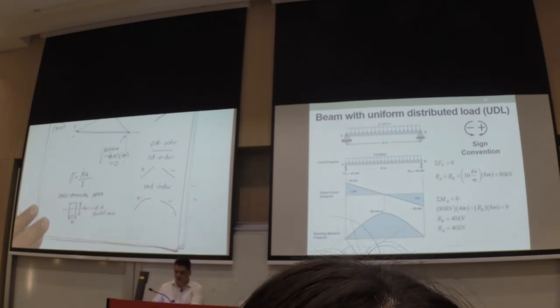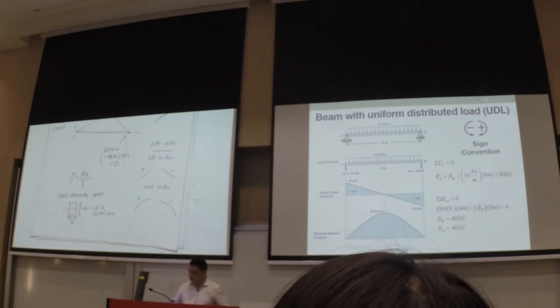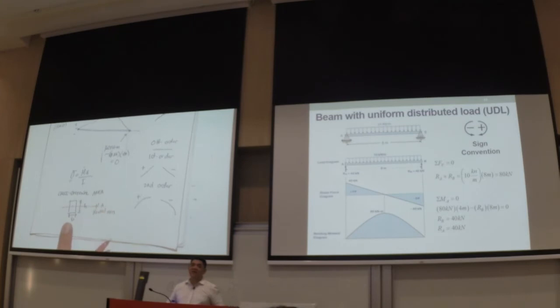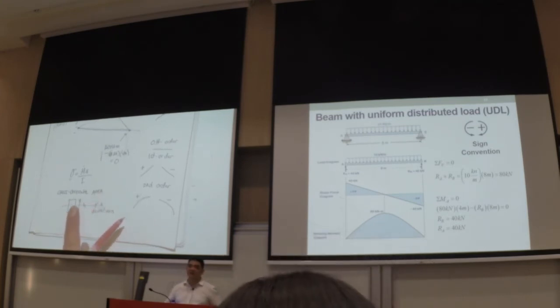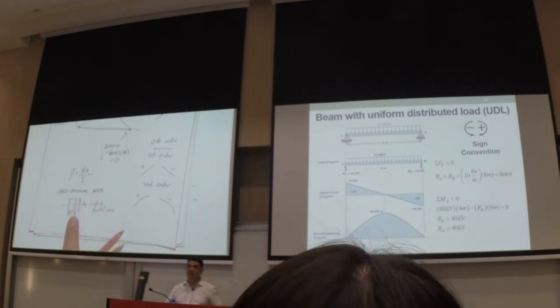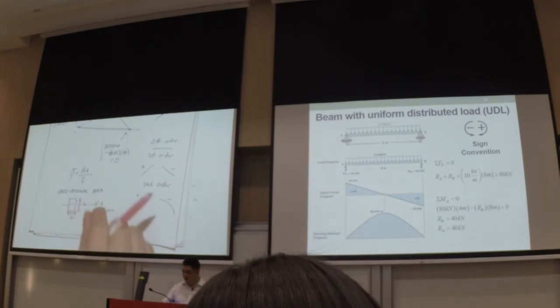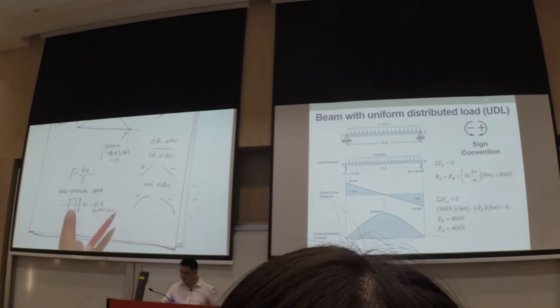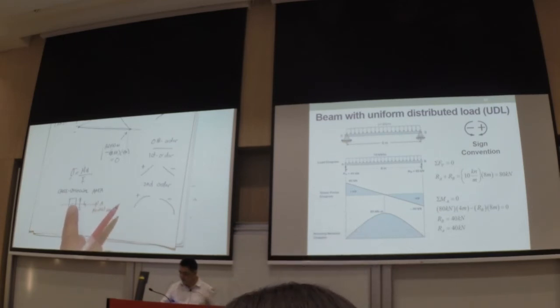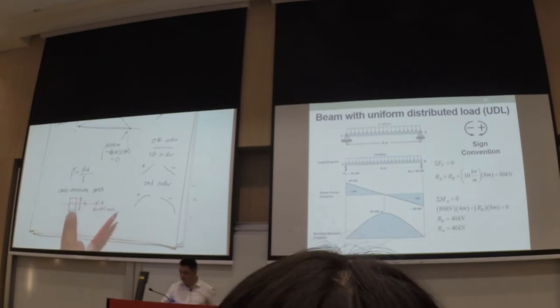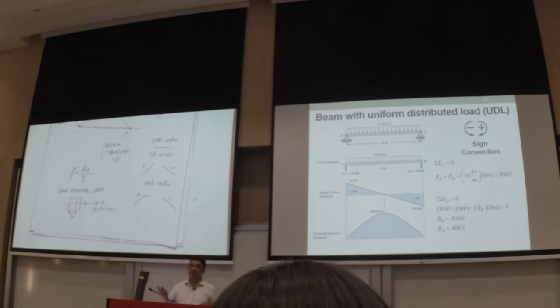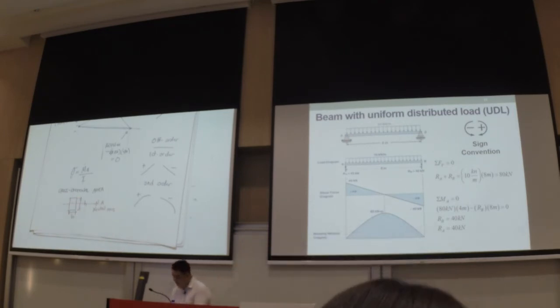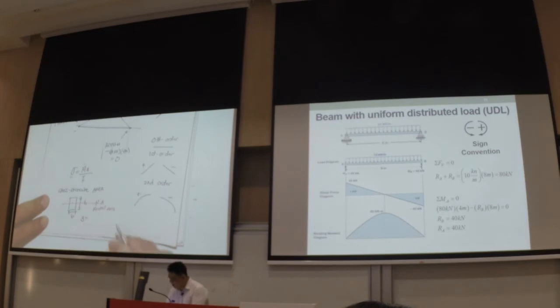Still, we're going to study a lot of that. So if we have a rectangular cross-section, your Y is actually the maximum distance from the neutral axis to the surface. Whether your surface is this one or that, we don't know. But for a rectangular cross-section, your Y here is 1/2 of that H.